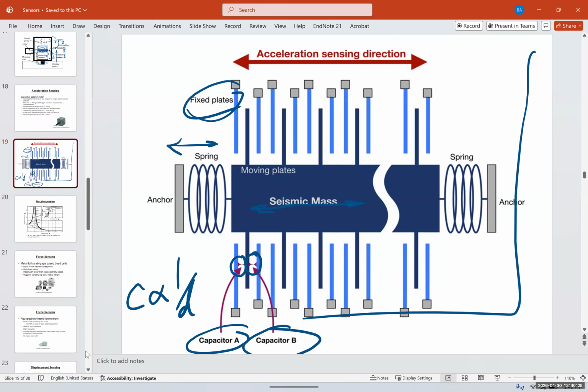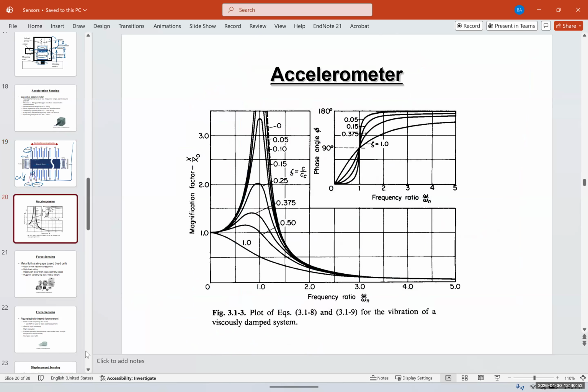You use this a lot again, and these are an older generation, I would say, in phones that we had. Nowadays, we use MEMS, and I'll explain what MEMS is. It's the exact same principle, but in a very, very small package. You directly build it in an IC using semiconductors. You don't need the mass and springs. You don't need any of these. Instead of the springs and these plates, everything is built out of a single material, which is semiconductors.